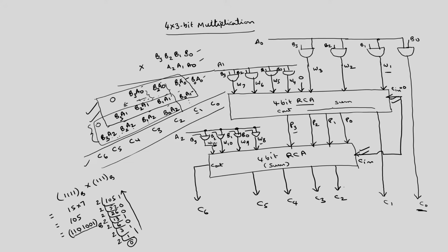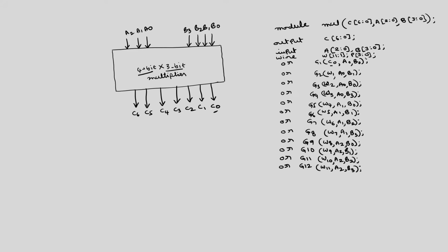So, up to here. Okay. Now, to get P3, P2, P1, P0, you have to instantiate this 4-bit ripple carry adder. To get the final result, you have to instantiate this with Cin equal to 0. So, we can assign Cin is equal to 0. Even you can define this wire for this Cin, because this is not external to this block. So, I am defining this wire as a Cin. I will assign Cin is equal to 0, then you have to instantiate.